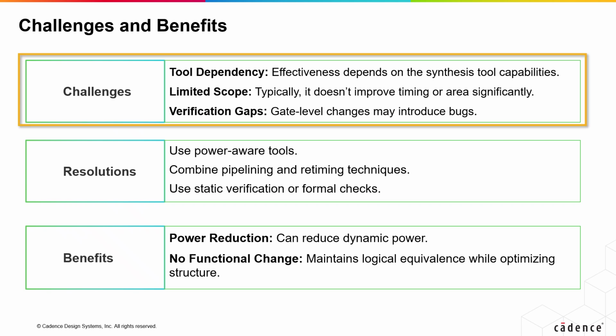The challenges in logic restructuring include that the restructuring occurs during the synthesis stage, so the tool's performance determines the logic restructuring effectiveness. Additionally, it does not much improve timing or area, and restructuring the design might introduce bugs that cause verification problems in the gate-level netlist.